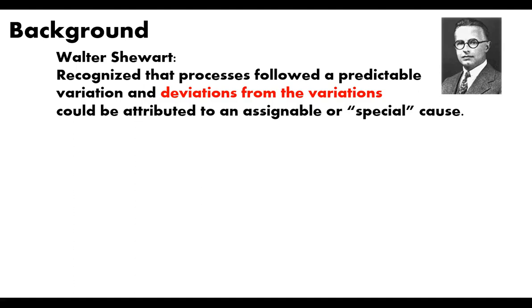You can have the most fine-tuned machine, and if you measure it well enough, you will be able to see variation. And that's one of the ways in manufacturing processes that you consider a machine more or less capable than another, with the same process happening on two different types of machine tools. And you'll see this throughout nature, that things will form a normal distribution over time, even with heights of people, with weights of people.